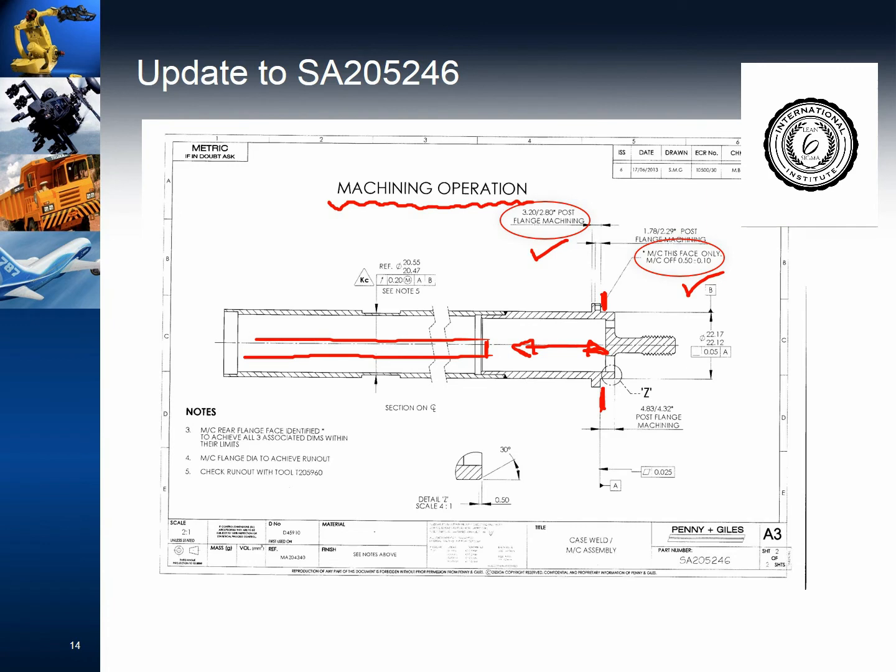A requirement obviously to do with the way the part performs or the way the part fits in its position on the plane. It's been modified without giving it a thought that it happens to be a datum face for the jig, and what they've done is kicked that distribution all over to the left that you saw earlier in the CPK diagram.